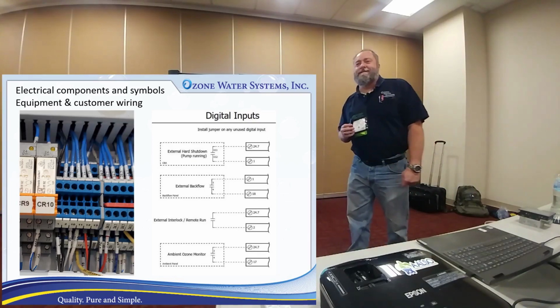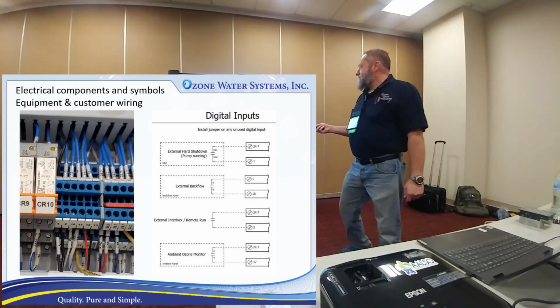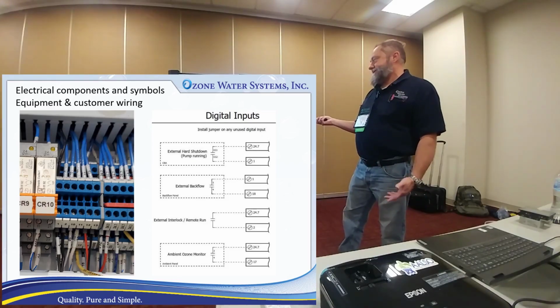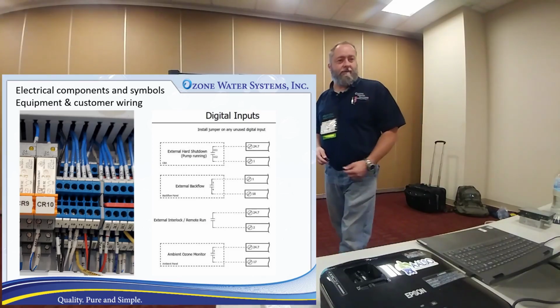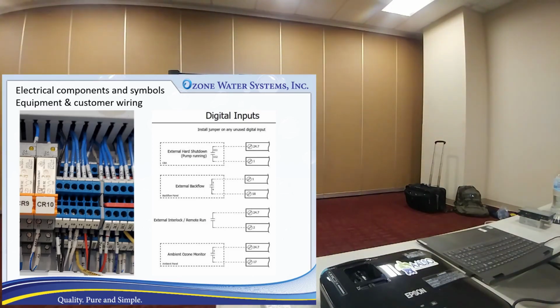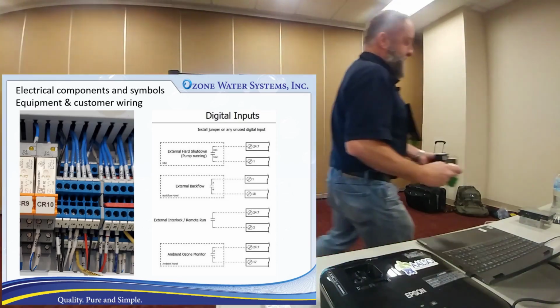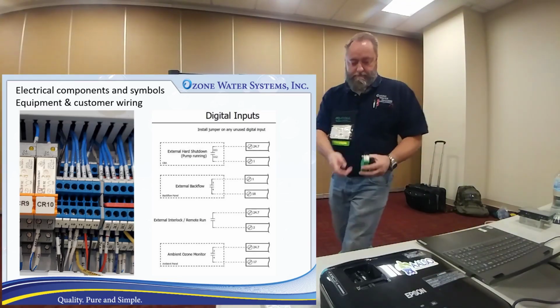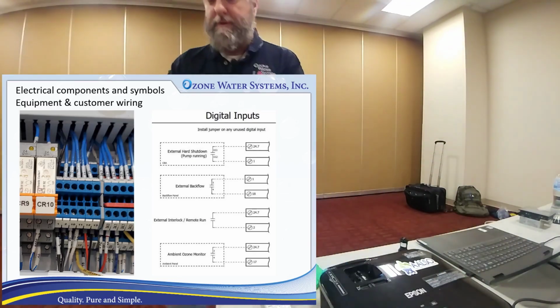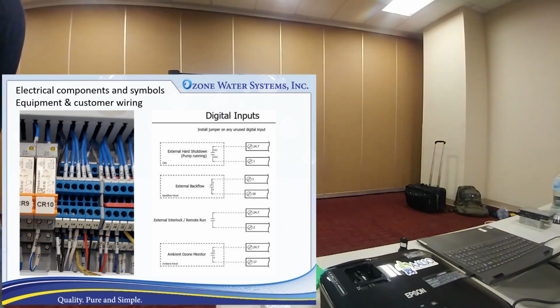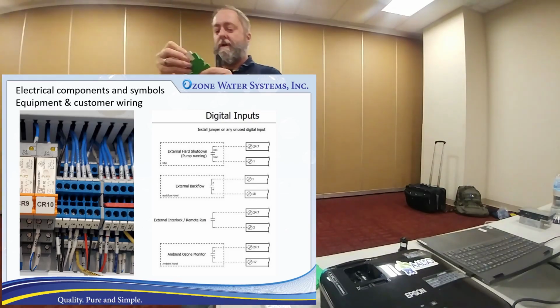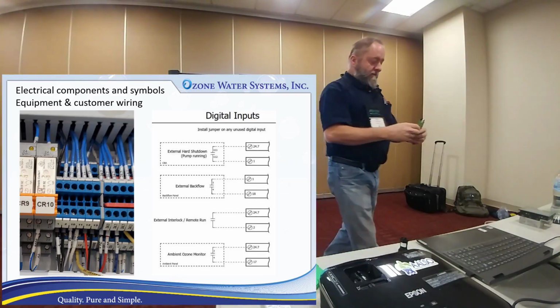No, they don't. These, if you needed to turn it off, you could. These little orange things are a little lever. You can actually do it on that one if you ever pop that out. But these relays, you can pop out so you don't have to replace the whole base if something happens to your relay. You can just push this little lever over, and it'll pop the relay out, and you can replace that if the relay has failed. You burnt the contact up or something. But no, they don't have a bypass.